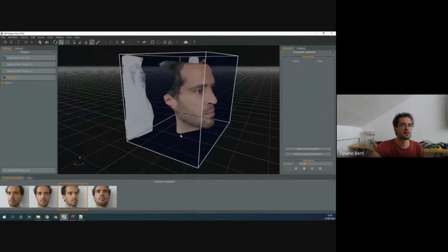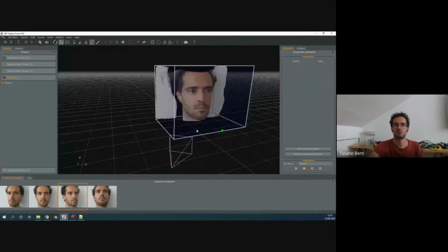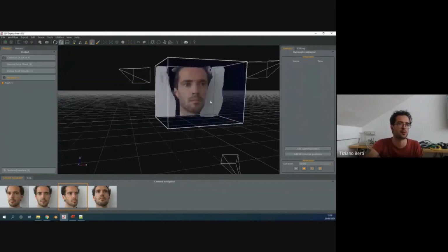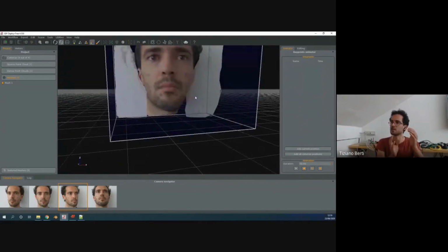So the more photos you get, the better the quality will be up to a point, but then it will probably be overkill. For this kind of easy object without undercuts, it will be fine to just use 4 photos. You can start with a very small project and see how to tweak it correctly. You can try a very tiny angle between the photos, see if a bigger angle works better or not, and try to find the correct settings.